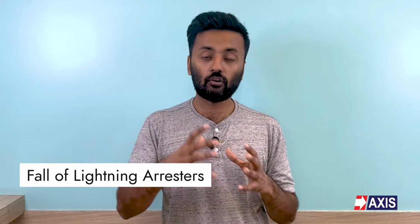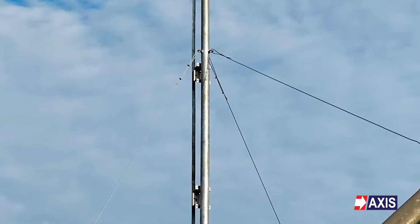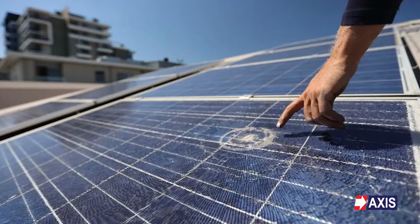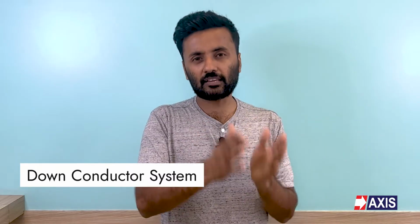Fifthly, the fall of the lightning arrestors. If the long metallic lightning rods or ESE lightning arrestors are not designed or installed correctly, they can fall on the modules and cause significant financial losses. Therefore, one should only rely on trusted technicians and tested equipment when designing and installing the lightning protection system for your rooftop solar plant. Now, let's discuss the down conductor system, which is the second part of external lightning protection.